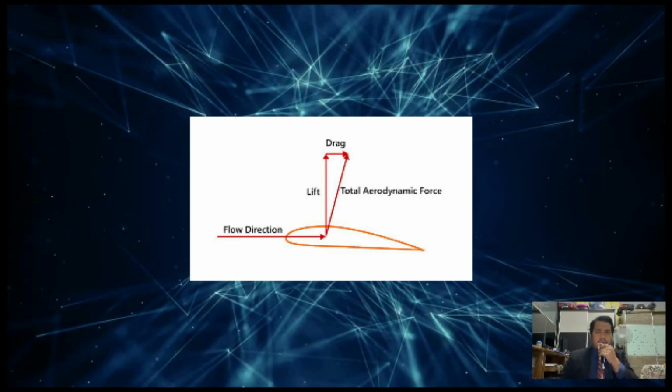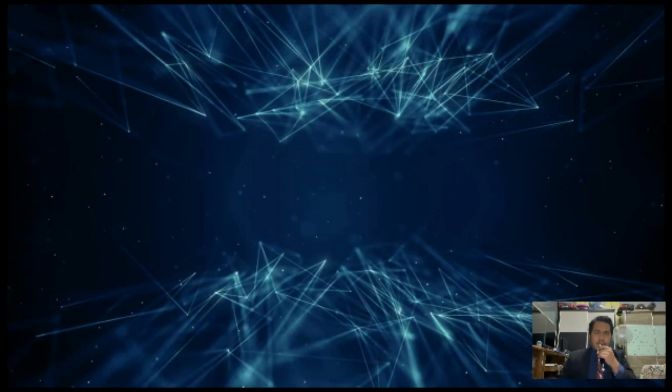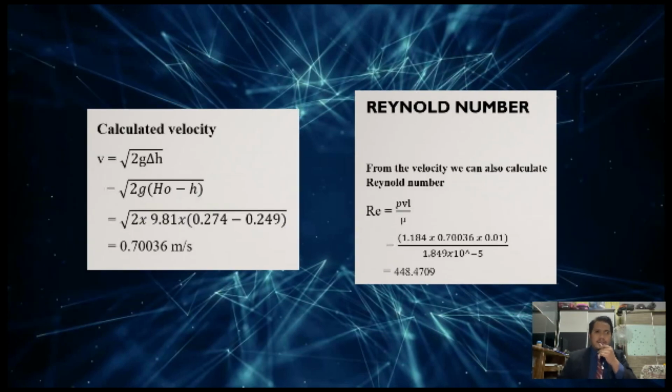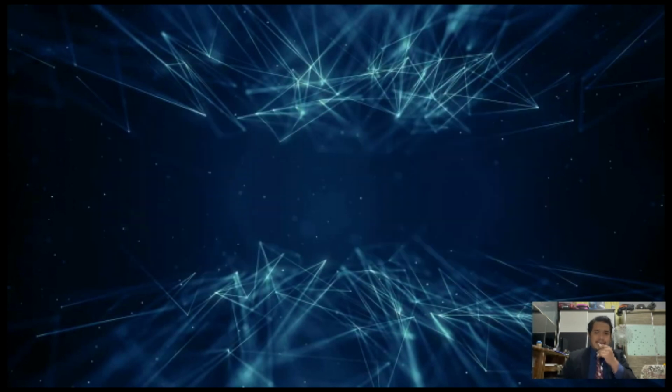We also have determined the velocity distribution for a flat plate. The boundary layer on a plate is generally affected by some factors, such as speed of the flowing fluid, Reynolds number, and the roughness of the plate. If the speed of the flowing fluid is increased, the Reynolds number will increase.